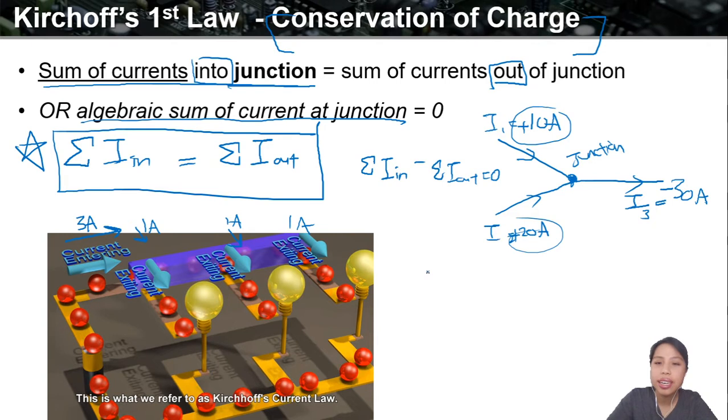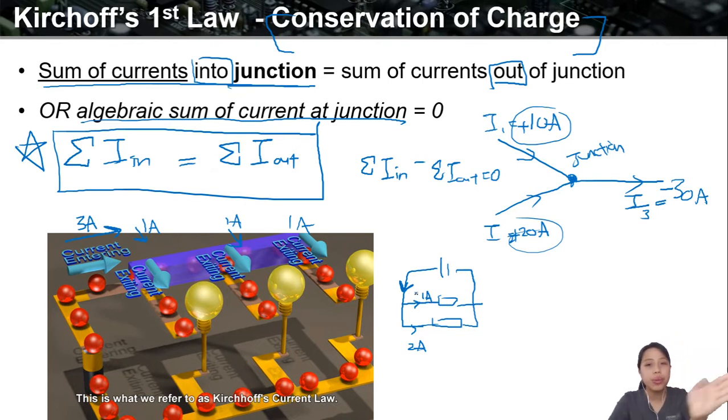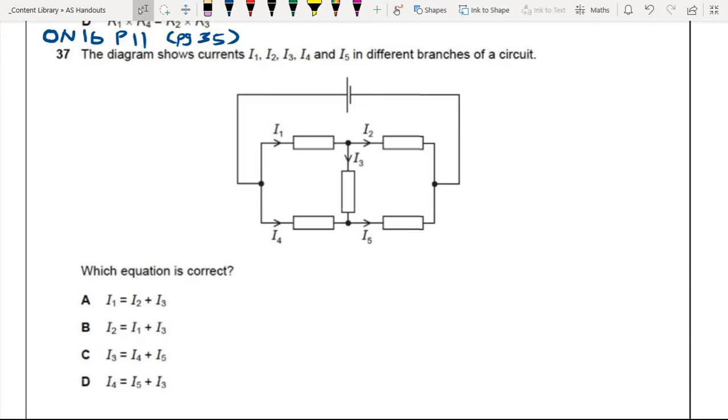Hey, you know already. Remember when we had parallel circuits, if they split like that, if the current here is some value, then here it splits to become, say, 1 amp, very big, and 2 amp, then what will be the current through the battery here? Something split into 1 amp and 2 amp, so this one must be 3 amp. It's the same thing that you know, just that now there's a name to it and a proper equation that describes what we are seeing. Now let's go look at some practice questions to help us understand this idea better.